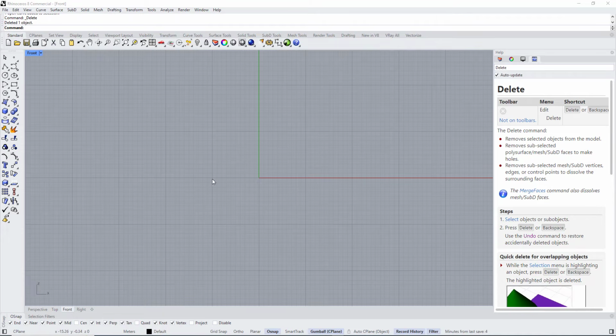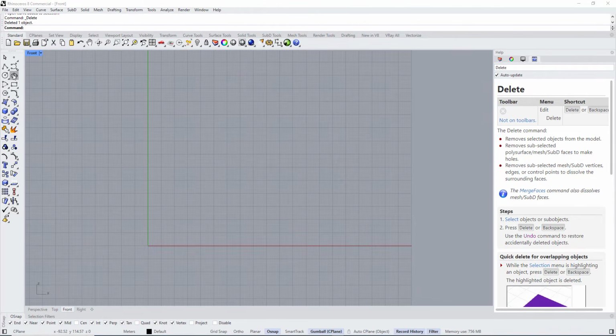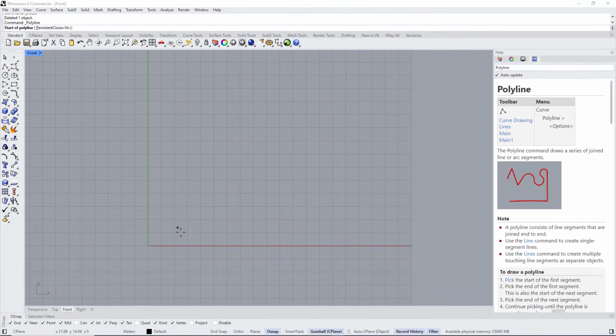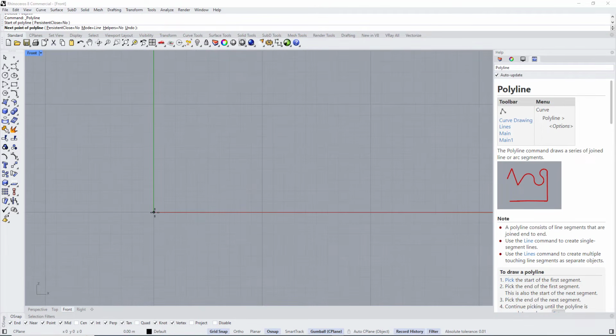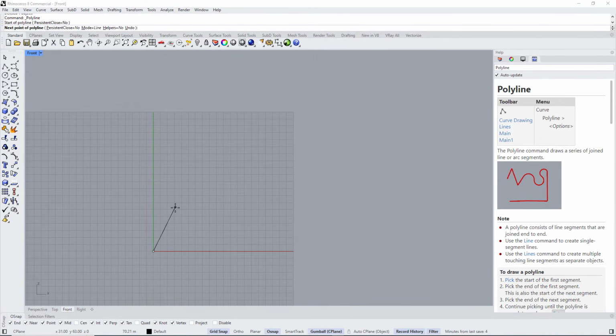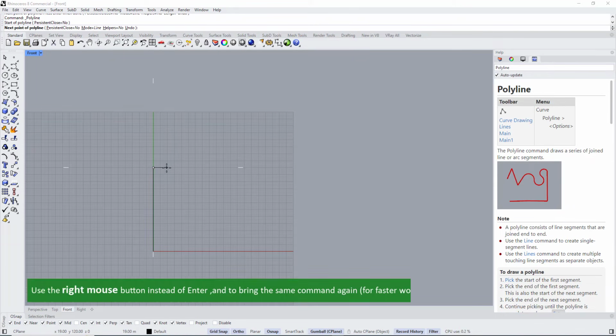So to model something like this, the first thing we need to do is to come in the front view and start drawing the shape. I will open the grid snap. Maybe the tower, press F8 to open the ortho. The tower height maybe 120 meters, for example, and the length maybe 17.